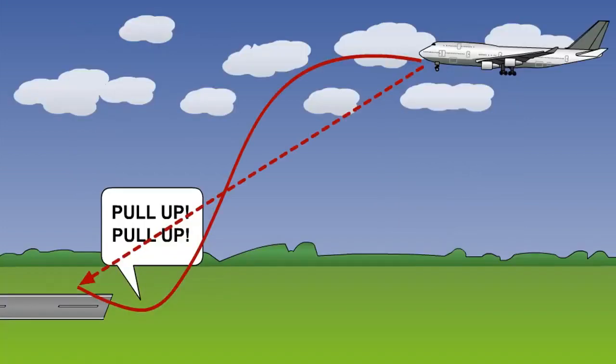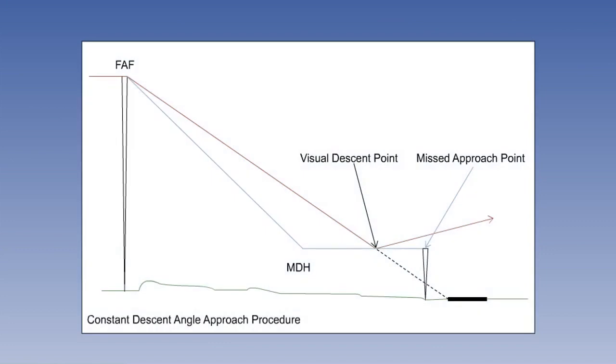Next, we will examine the terms for conducting the approach. Owing to their size, weight, and proximity to the ground, airliners on approach, whether precision or not, should be flown in a stable manner where events, flap settings, gear down, speed, and height adjustments are undertaken to maintain a precise and carefully controlled environment. Many operators use the stabilized approach technique, where the parameters for events on approach are strictly defined and with the requirement that a missed approach be initiated should the pilot exceed one.